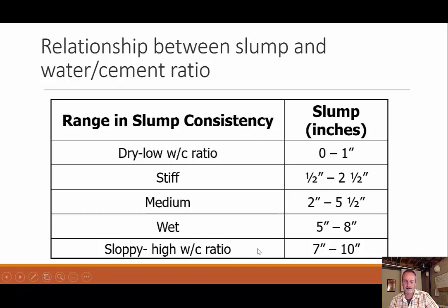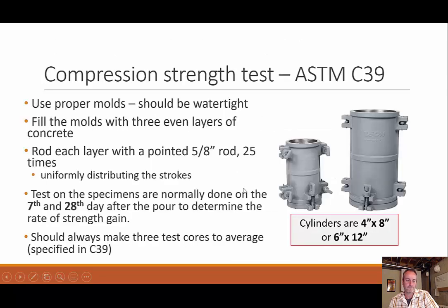Like, we haven't really talked, I don't know if we do talk about this, but like shotcrete, if you're going to be pouring it into something and shooting onto a wall, of course you'd have a very high slump for something like that. So application may depend, but in general, we're shooting more for these middle, medium type of slumps.